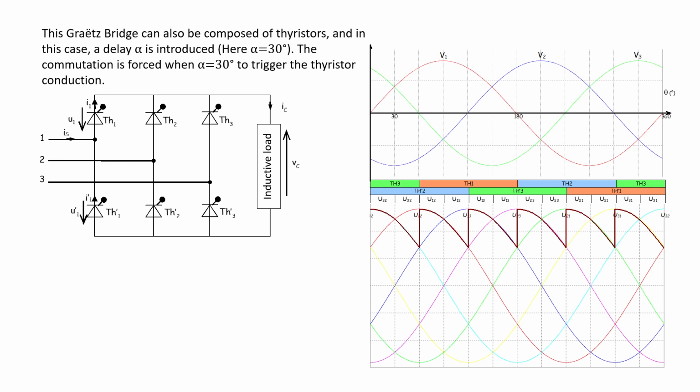And then for thyristor, we can control it by firing a pulse to turn on a particular thyristor. And there is a certain sequence in which you can turn on thyristors so that the waveform of VH out of the bridge would be like this.